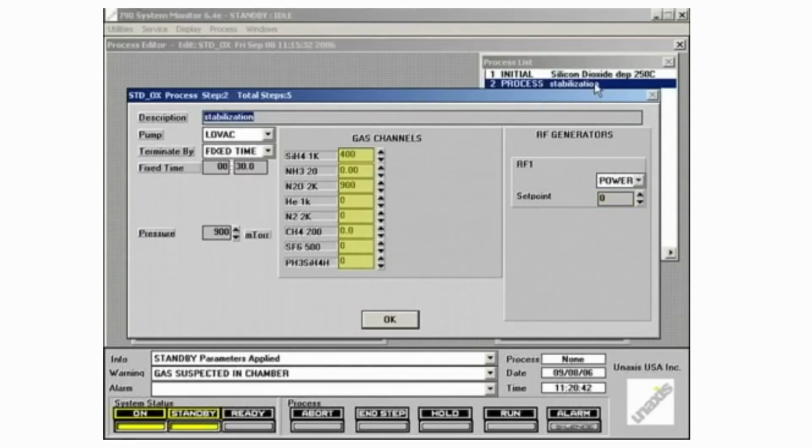You should also set the gas flow rate for each gas here. Flow rates are given in SCCM. Set the pressure you want for the process in units of millitorr. The system is optimized to run between 900 and 1100 millitorr.